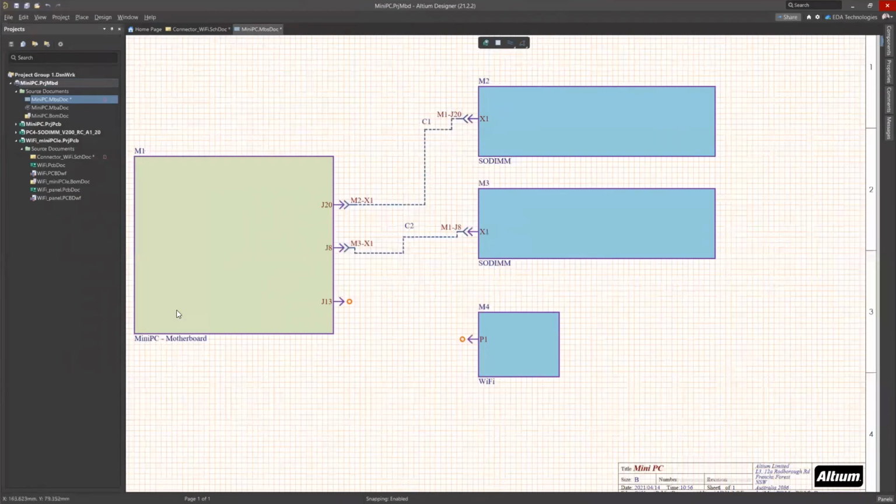So now that you've got your module in and you've got your two connectors defined, how do we actually define the connection between the two boards? Over here, we can say add wire, or if I hold, you can see you can choose a wire, a direct connection, cables, or harnesses. A harness is where you say these three boards are all going to connect into a harness that connects onto this connector here, for instance.